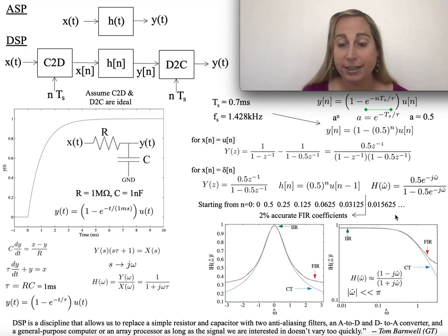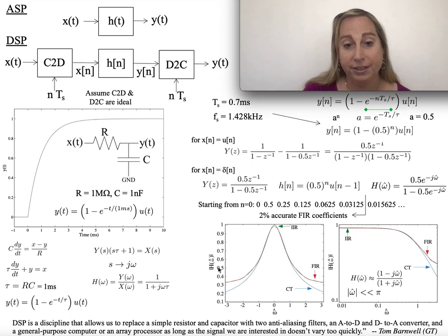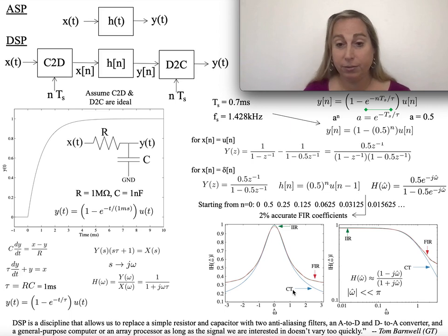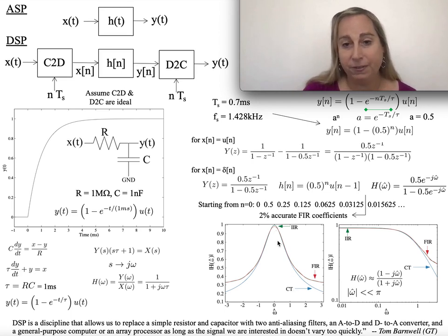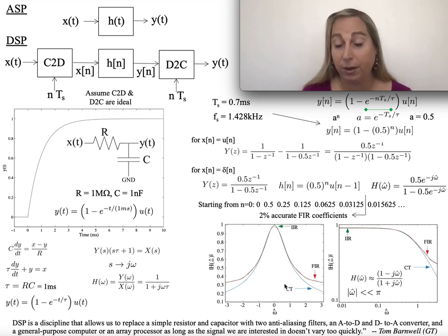And in fact, you can take a look at what the different frequency responses would be. And that's what's plotted down here. This is the frequency response of the continuous and the discrete, and then the continuous inflected back into the discrete axes for you. And what you find is that the IIR and the FIR one agree very closely. There's a slight miss at the top, but otherwise they agree quite well all the way throughout. You'll notice that the IIR and the continuous time agree really well up to the peak and go all the way down to a point, but then stop.